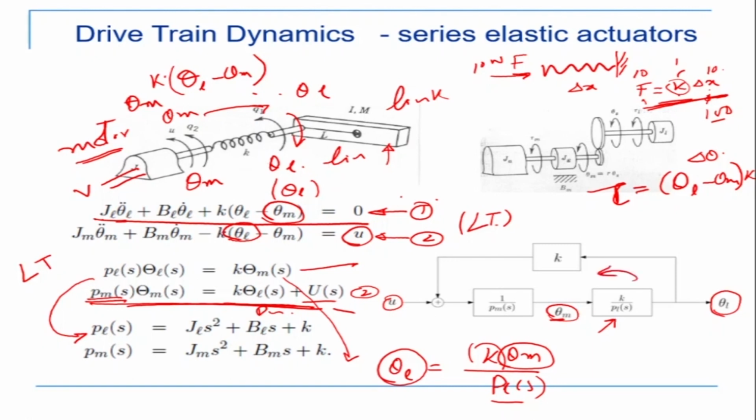And it is closed loop control, so the K is coming back this way now. Okay. So if I find the transfer function here, how do I find the transfer function of this? I multiply this into this. This is in the same loop. And if this is my G(s), that's my H(s).